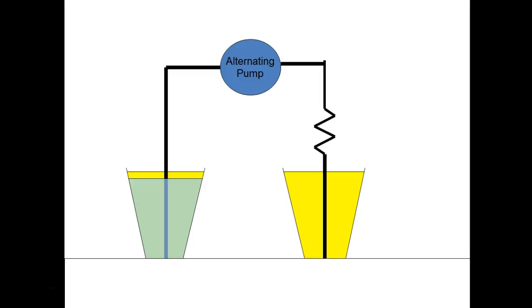Does that make sense? What's really interesting is that when we first put voltage on a capacitor that's discharged, it acts like an empty bucket and the water comes flowing in extremely fast. But as the bucket fills up, the water slows down until it tops out. So when we have 0 volts across the capacitor, the current flow is at its maximum.